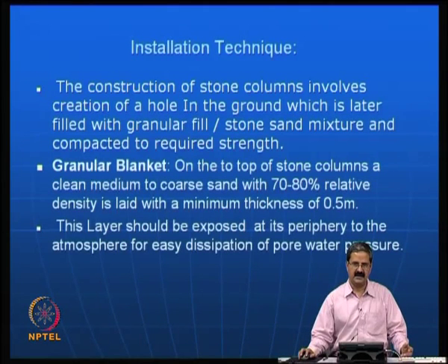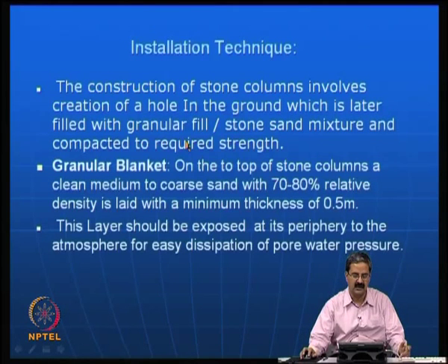Nowadays we see that big companies, particularly Keller and other groups, have come forward and are trying to do something in India. But in the previous times, in the 80s, we had the creation of a hole in the ground which is later filled with granular fill or a stone sand mixture and compacted to the required strength, say for example the friction angle of the soil. That is what people were doing. They did not have sophisticated methods. Then you have to construct a granular blanket, as I just mentioned, as per the IS code.